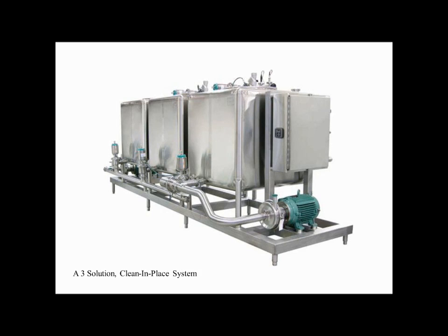Just a shot of a clean-in-place system. This is the kind of thing you'd have in a winery now, so that you could use 3 solutions, so that you could recover them, and so you could filter them and use them again and again and again. And so at some point we'll start building small systems like this that recapture the cleaning water and use it many times. And that allows us to reduce our water footprint dramatically. And if we've chosen the chemistry right, the inorganic piece, we can use that over and over again as well. So we're trying to lower the water input, we're trying to lower the chemistry input, and we're trying to use our cleaning solutions many, many times. And one of the central pieces that enables that is a small CIP system.